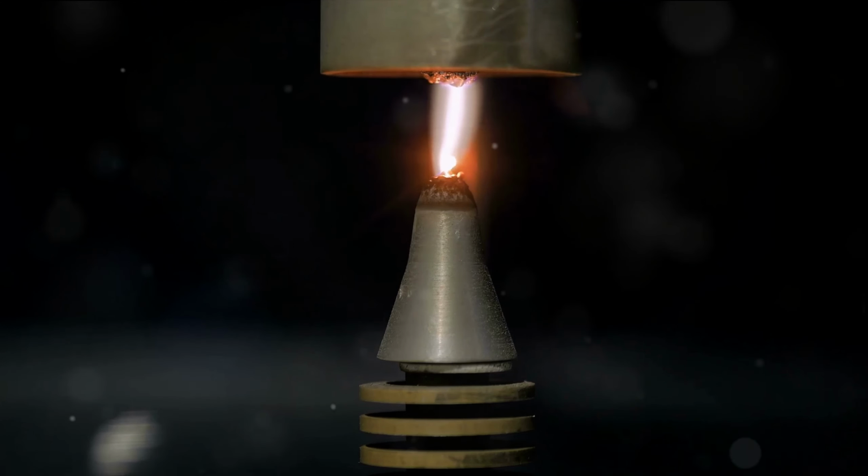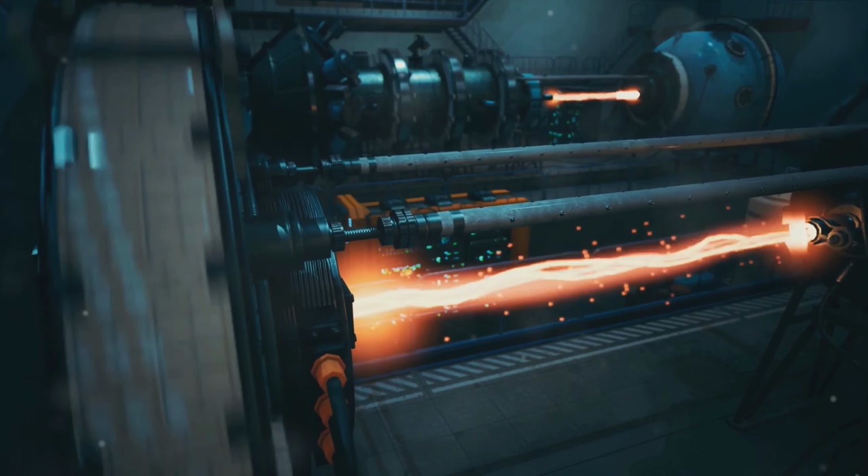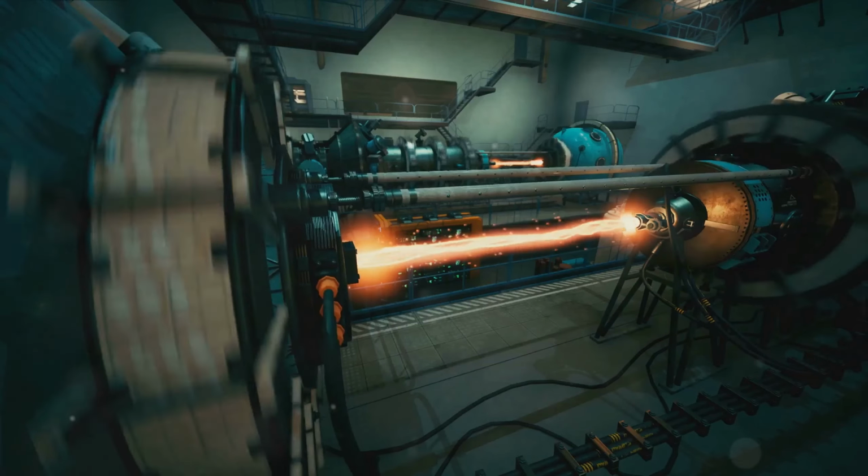It offers a higher exhaust velocity compared to traditional chemical propulsion systems, which translates into more efficient fuel usage. However, challenges persist, such as the requirement of high power input and the difficulty of achieving stable plasma states. Despite these challenges, ongoing research and advancements in power generation and plasma physics are paving the way for the practical implementation of MHD propulsion in future space missions.